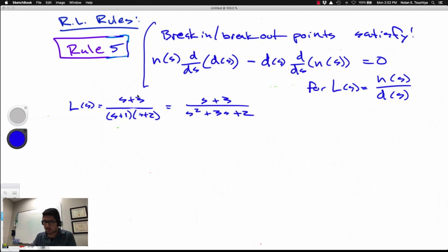Okay, and so written this way, the first way, it's very easy to compute the poles and zeros of L of S. We can see that first n is equal to 2, m equals 1, right? There's 2 poles and 1 zero. Furthermore, the poles are at -1 and -2, and the 1 zero is at -3, right? So that's why writing it in this way is more convenient.